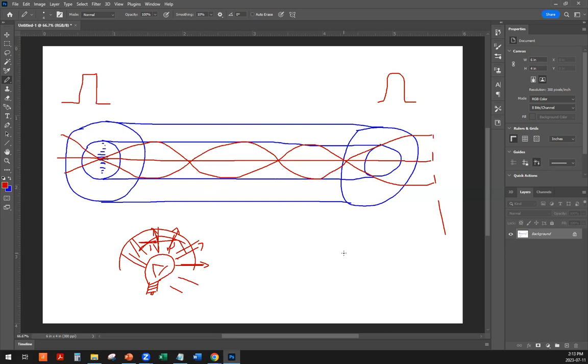The previous scenario we would consider step index, because we are stepping from one index to another. And this one here is called a graded index fiber, because the index is slowly decreasing in number as we go towards the outside. So you're going to hear a lot of that terminology, graded index fiber. And it only works with multi-mode, because single mode has just one mode, so there's no need for a graded index there.